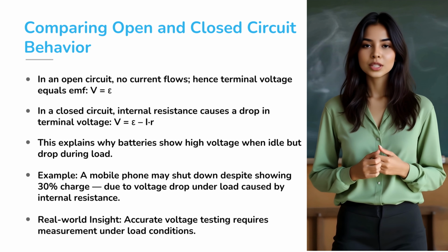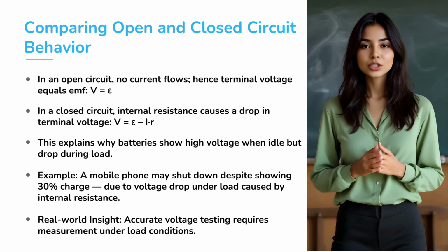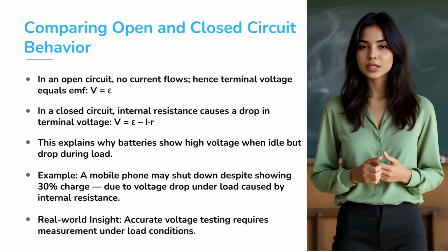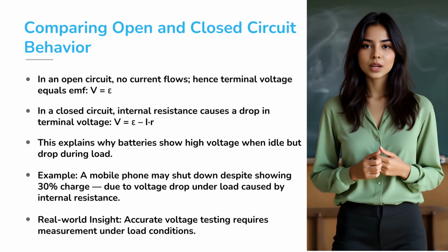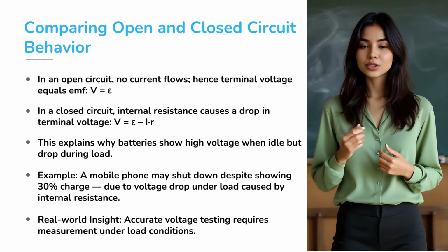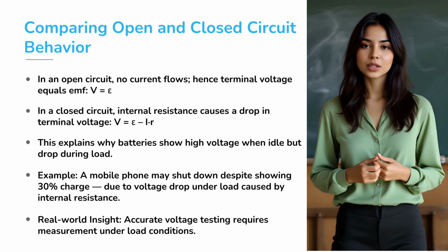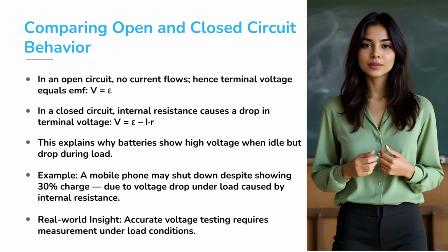This means the voltage available across the load is reduced because part of the energy is being used to overcome internal resistance. Real-world insight: to measure a battery's health accurately, you need to measure its voltage while under load, not just when idle.